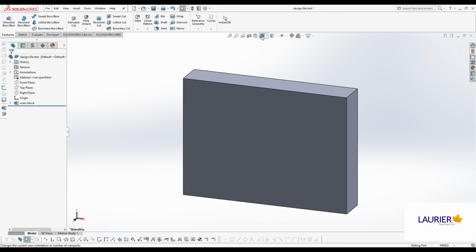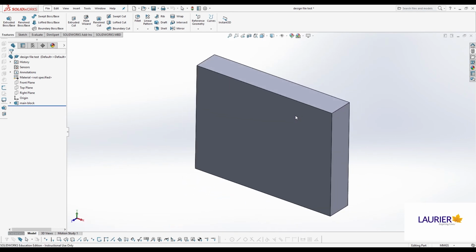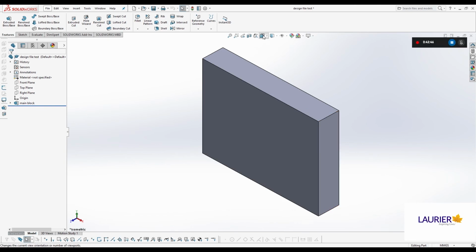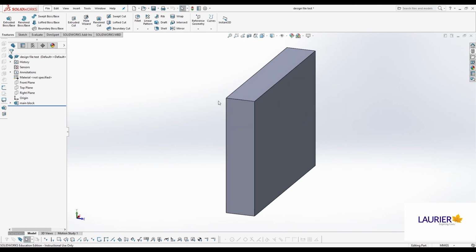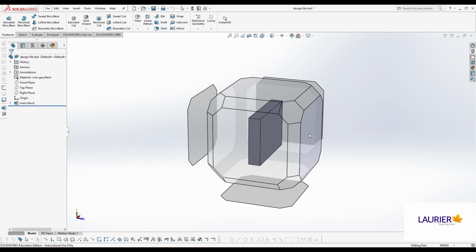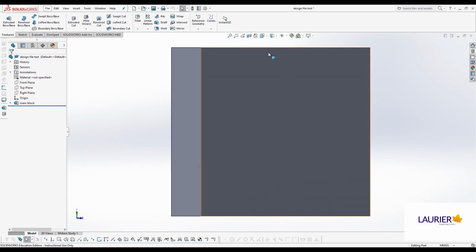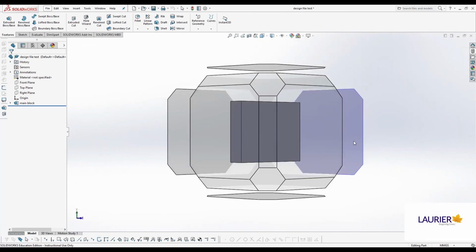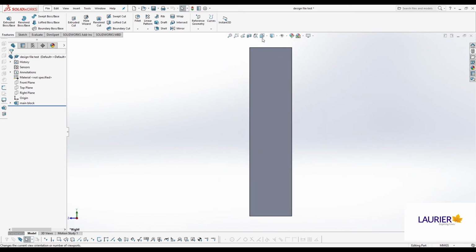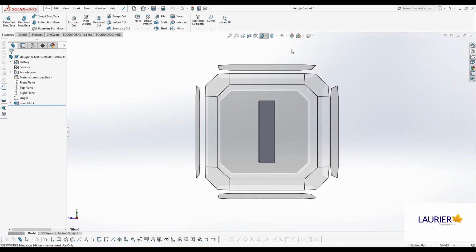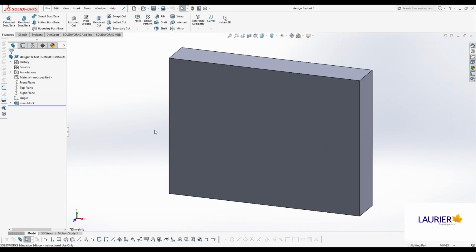We can go play with our cube tool there, the view orientation tool, as it's more properly called. And we can hover over a side, and up in the upper right, we'll see a preview of what we're going to see if we click on it, and it'll orient it that way. But if we want to kind of just examine it, there's an even better way, and this is probably one of the most fun tools in the CAD.